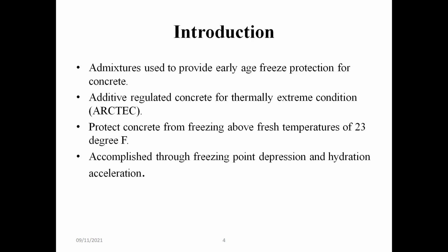Admixtures are used to provide early age freeze protection for concrete. Additive regulated concrete for thermally extreme conditions is protected from freezing above a temperature of 23 degrees Fahrenheit, accomplished through freezing point depression and hydration. Here, I would like to add that admixtures are not only added to alter the workability, they are also added to depress the freezing point in concrete.